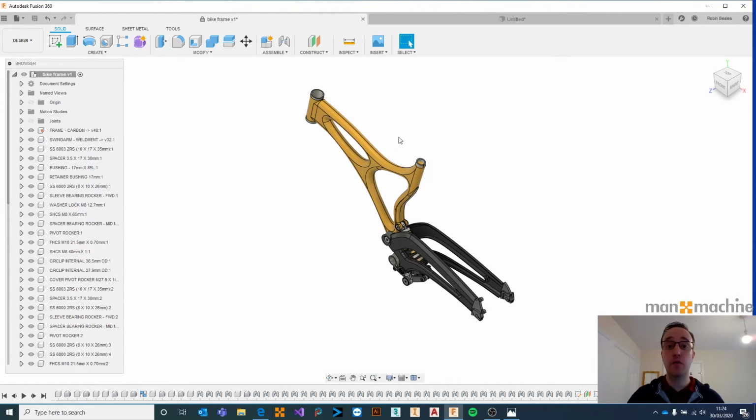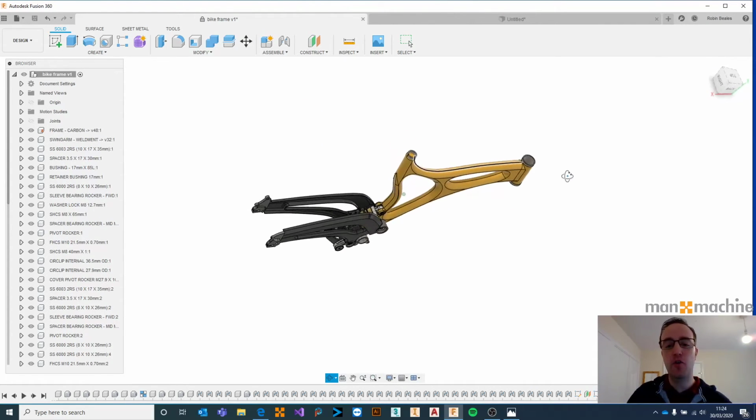The only difference is you've also got to hold down your shift key on the keyboard. Just above the control key is the shift key. It should say the word shift as well as have an up arrow on it, normally just below your caps lock. If you hold that down and then hold down your middle mouse button, it will allow you to orbit.